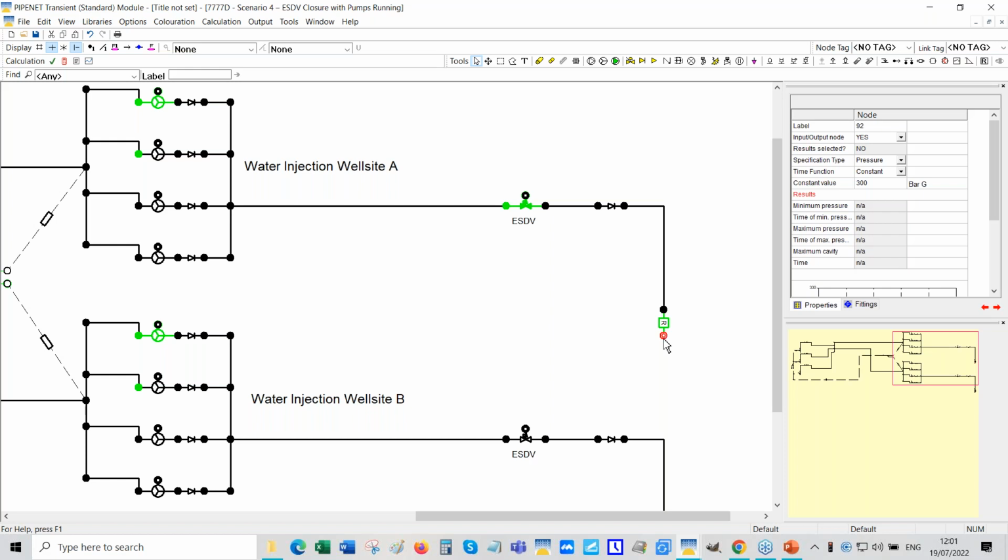What can happen sometimes is that because the pipes are elastic, when you close an ESD valve here, the pipe can contract because we're working at a high pressure, and you can get a flow back into the well. And that's highly undesirable because when it flows back, it'll undoubtedly bring sand back into the system. And that is something we should avoid. And because of lack of time, I'll simply show the effect of this.